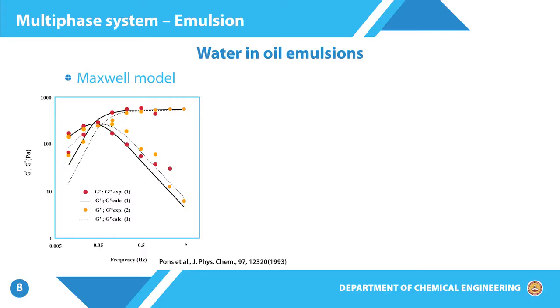But in this case, we are only probing a limited range of frequency, and so glassy response in this case therefore only implies the response with respect to droplets and not really with respect to the individual phases. And so, this is something which we should always remember, that whenever we do rheological analysis, quite often we are only looking at the limited time or temperature or frequency range, and therefore, the conclusions that we are drawing regarding its behavior is only valid for that range, and beyond that there will be other relaxation processes which would be